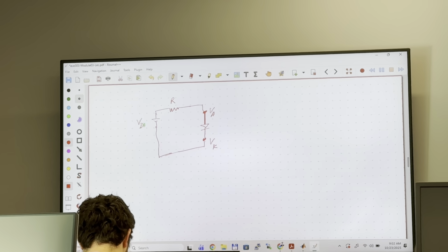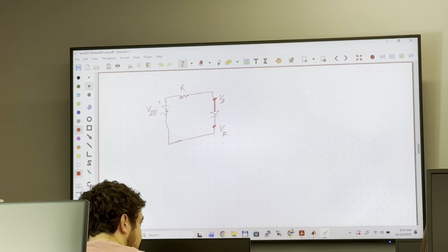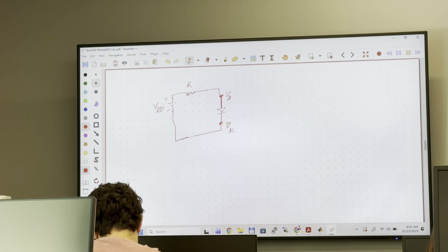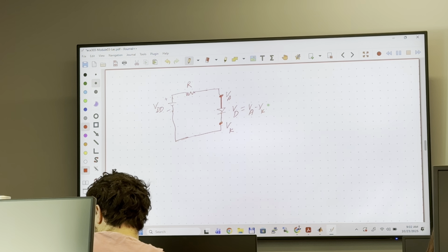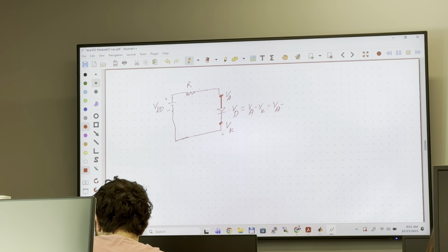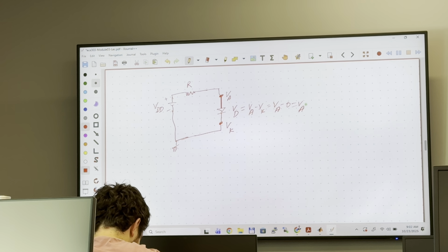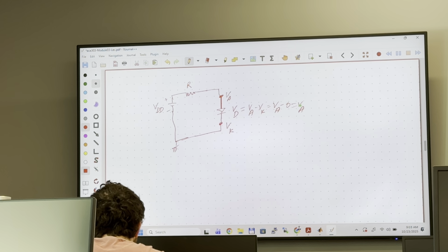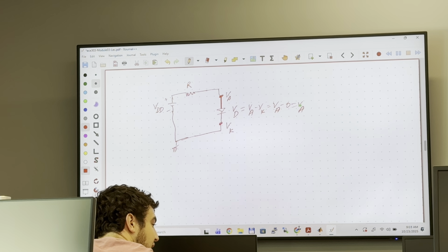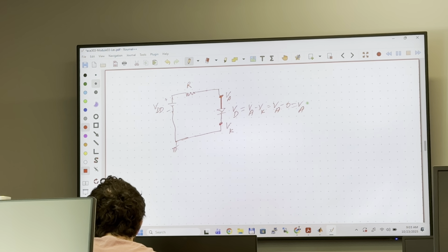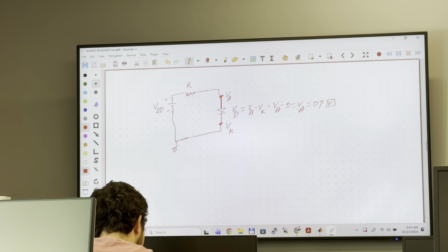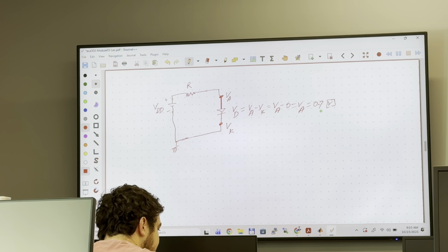is VDD. So positive VDD. So the voltage across the diode is going to be VD, which is basically anode voltage minus cathode voltage. V anode minus V cathode, which is connected to ground, so which is 0. It is simply the anode voltage. For a practical standard diode, what is the voltage drop across the diode that we consider? Standard voltage drop: 0.7. And we get this 0.7 volt.